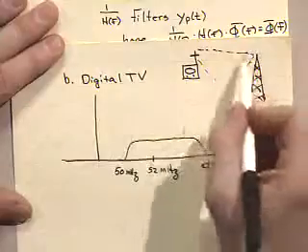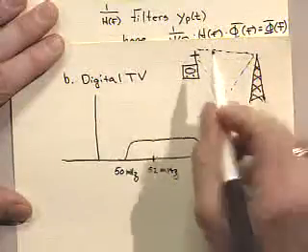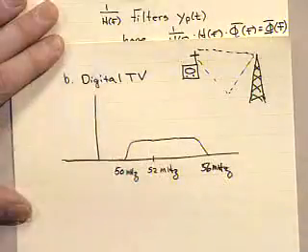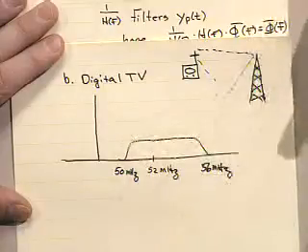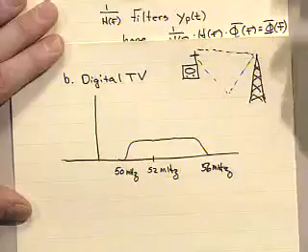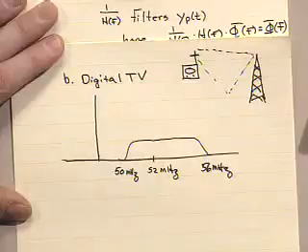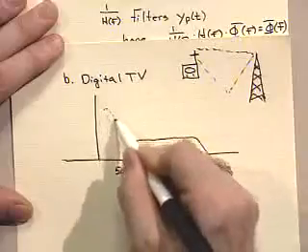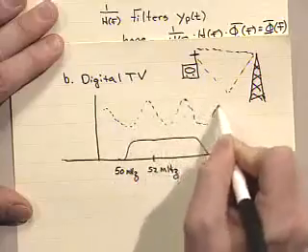So you'll get a version of the signal plus another version of the signal, maybe of the same order of magnitude, but delayed. And at certain frequencies of transmission, that delay will correspond to being 180 degrees, which will mean that the delayed path has a negative of the signal that you're receiving. So it'll actually cancel itself. And this is called multipath distortion. So what's going to happen when you do this is you're going to see the channel looking like that.